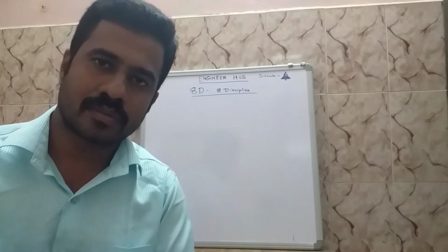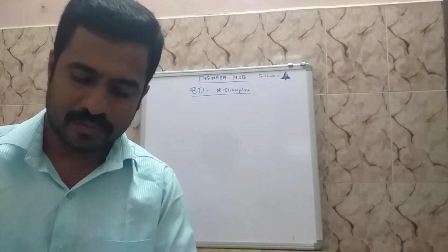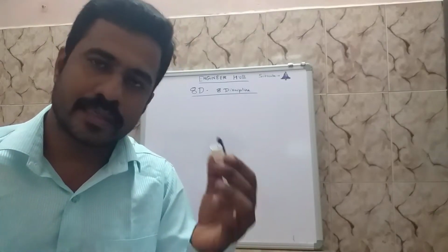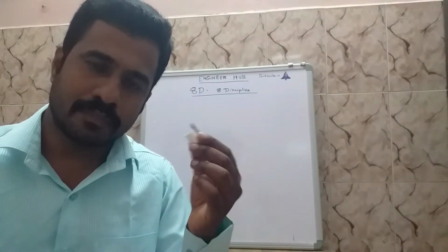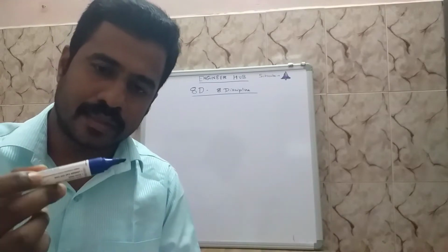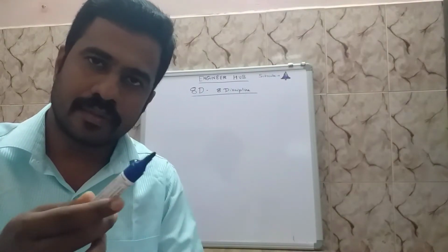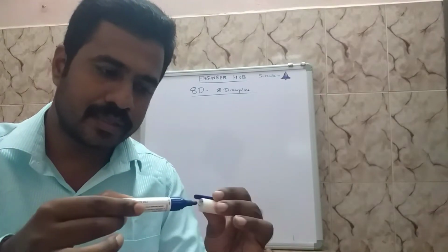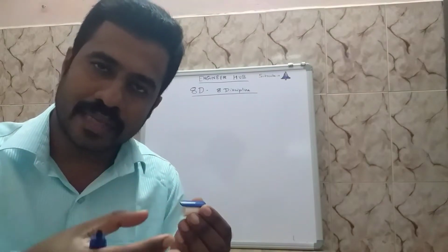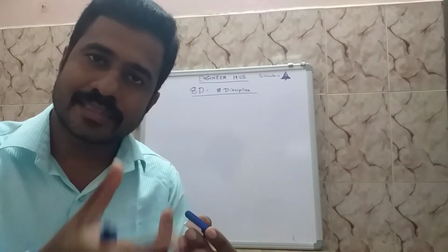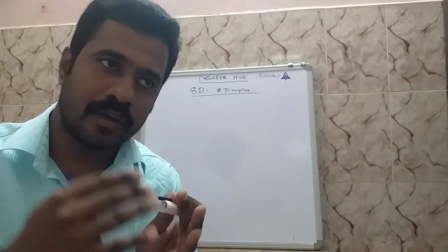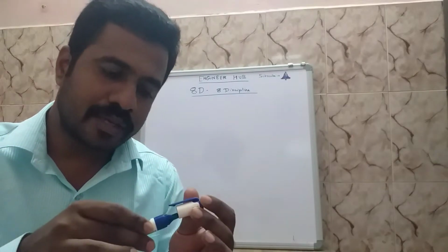Suppose there is a complaint regarding this cap itself. There is a specification of this product. The diameter should be perfect, as per the drawing. Suppose it's given as 10 mm, and the fit should be below 10 mm. Then only can it perfectly match and get fit. If the diameter or the length exceeds, or it gets compressed, so instead of 10 it is 9 or below that, then it may not fit into the product.